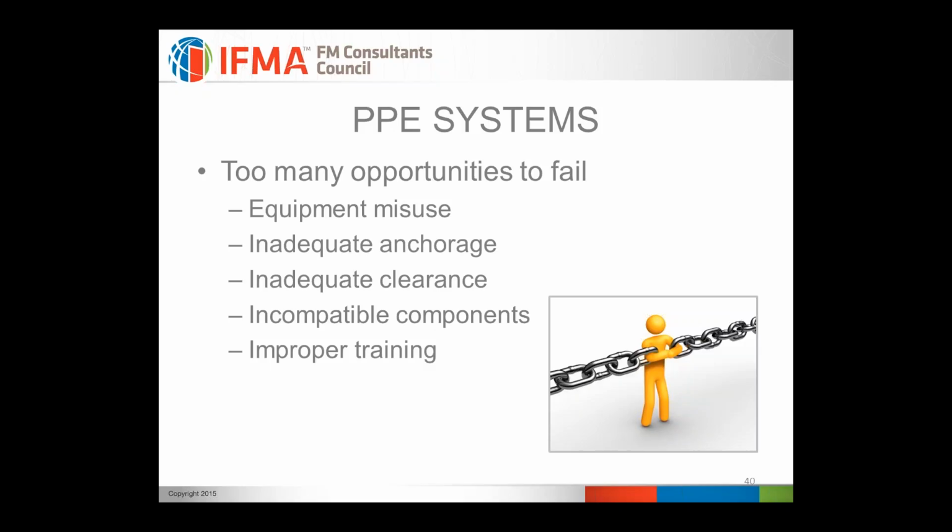They would hit the ground, and they just don't realize it. They either don't think about it or they don't know what would happen. So those clearances are oftentimes grossly underestimated. If you don't have at least 12 feet, 15 feet of vertical clearance between your feet and the ground, an active fall protection system is probably not the best answer for you.